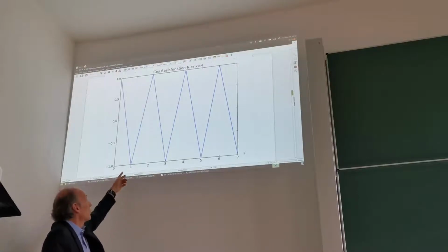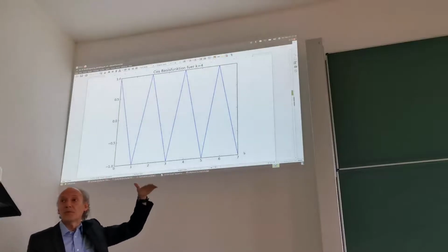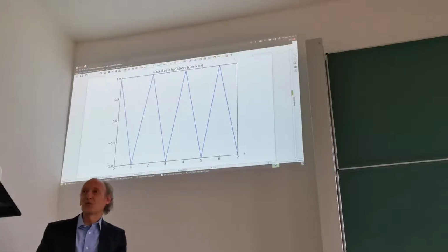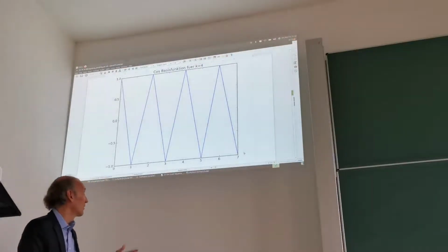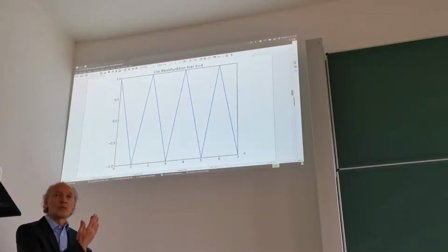So when we go to k equals 8, then we have a constant sequence of 1s. It looks the same as DC. There's no change at all. DC for direct current, remember. And this is also part of the symmetry around Nyquist.